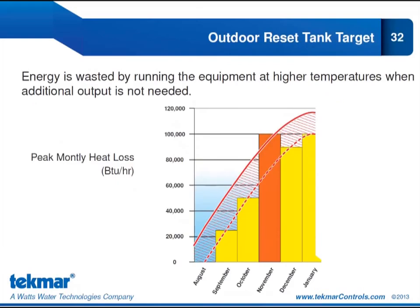So let's take a look at how outdoor temperature reset certainly helps us, but doesn't go all the way. If we look in red, this would be my reset curve. Now my reset curve works really well for the month of November, but it's not working so well for this shoulder season, September, October, and it's even supplying more heat than I need in December and January.